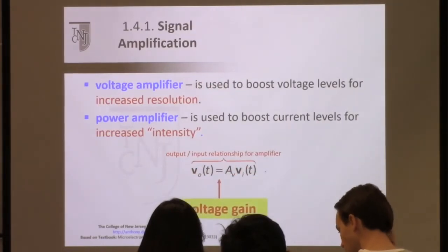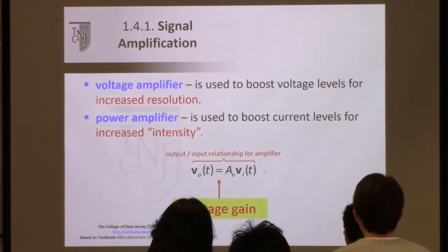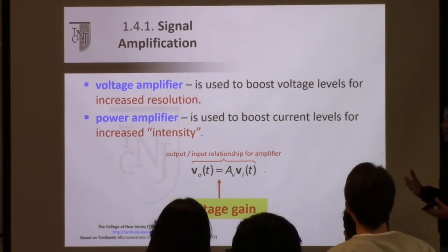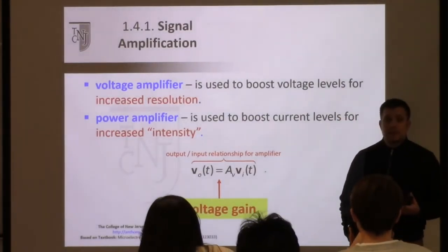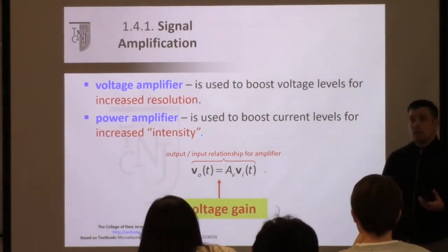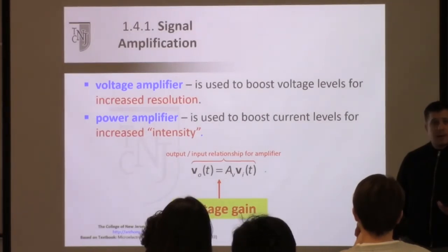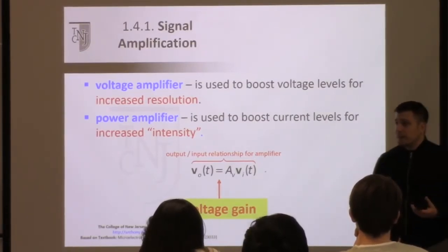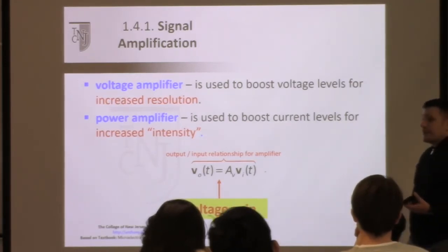We talked about this already, right? There's voltage amplification and there's power amplification. Both are often needed. Both play different roles. Voltage amplification is going to be more important when you talk about things like instrumentation. If you're working with computers and data, often that's what you're more worried about: is the resolution appropriate for the application that we're looking at? Power amplification is more about driving loads.